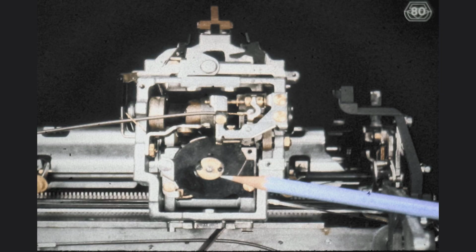When we reassemble the plate that sits underneath the rocker and holds the rotate spring in its cage, it is absolutely necessary that we mount the plate perfectly centered around the rotate pulley hub, as indicated. The slightest bind would interfere with the movement of the element and retard its operation during printing cycles. At this point, see if you can trace the force stored in this rotate spring from the rotate pulley hub all the way to the R5 bail, or cam follower.